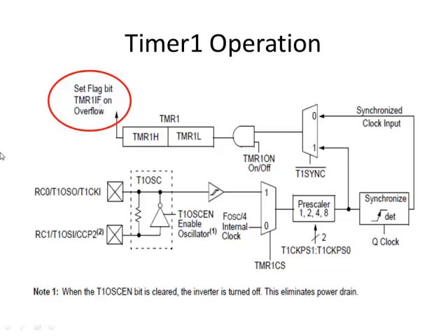It's the Timer 1 interrupt flag, and I'm going to call it an overflow flag because it makes more sense. Okay, when the overflow flag is set to a 1, that means that the timer counter has rolled over or timed out. That means that this went from all ones to all zeros. And we can test that bit with an if statement, or the timer can generate an interrupt. For now, we'll just test it. You can either use an if statement or you can use a while loop, just kind of like we did when we were waiting for the analog to digital converter to complete a conversion.